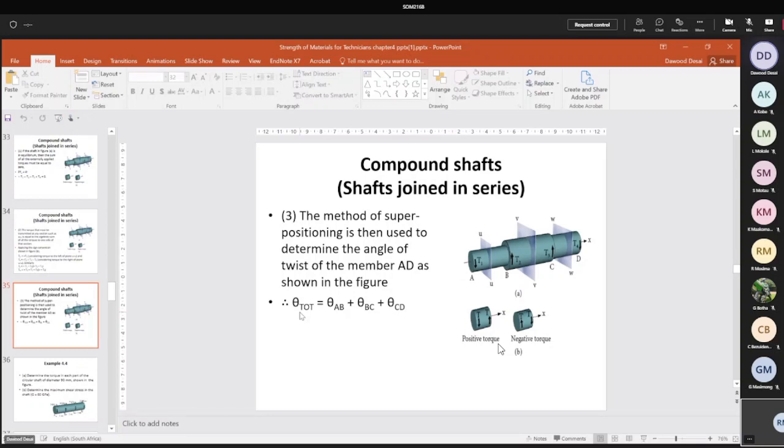Yeah, we're twisting. So total angle of twist is equal to the angle of twist in each section, like we done yesterday. What is the angle of twist? It is got from the normal formula, T upon J, the first formula I gave you, the three things. The general formula, you get it from there. Very, very easy. Are you guys with me?